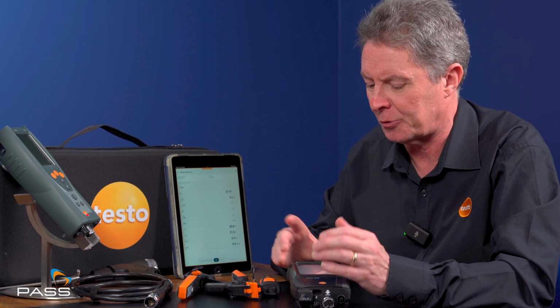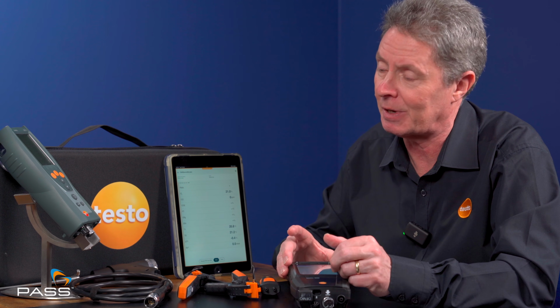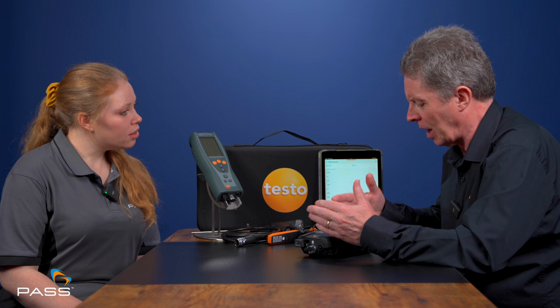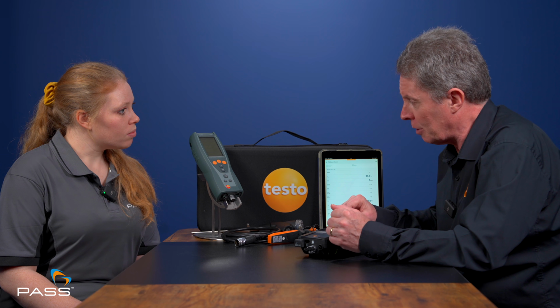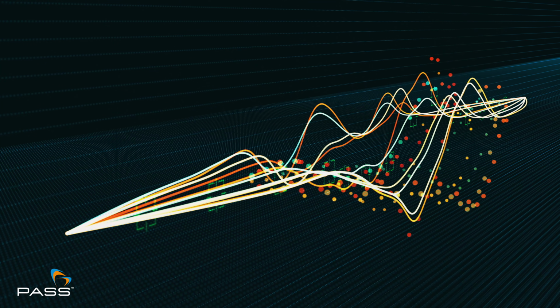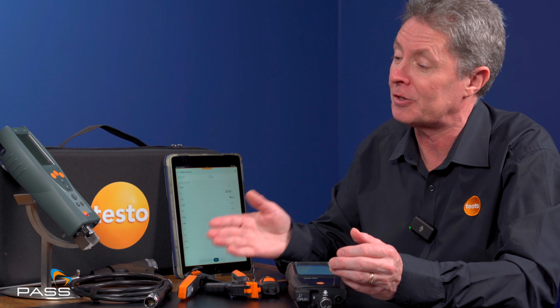There are other analyzers out there that do it differently, but we believe the two electrochemical sensors in these are the best way to do the combustion readings. Why is that? There are benefits. If you look at other technologies, if you're measuring CO2 directly, you can be measuring on the wrong side of what's known as a stoichiometric curve, and that can lead to errors. We believe this is a much safer method: measure the O2 and the CO and then derive the CO2 measurement.